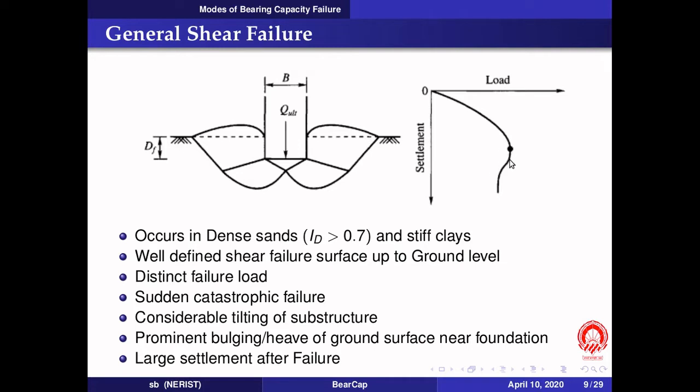And there will be excessive settlement that will go on after the failure has occurred. You remember the stress-strain curve of dense soil, dense sand in a triaxial test. So the load-settlement curve looks similar to the stress-strain curve of dense sands in this case.